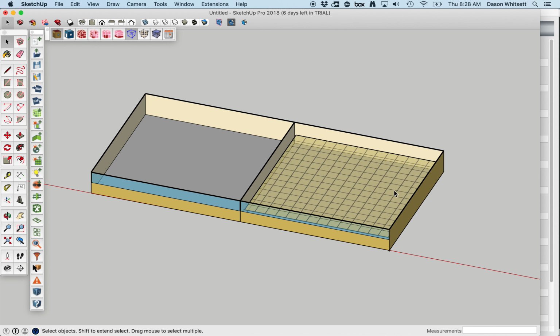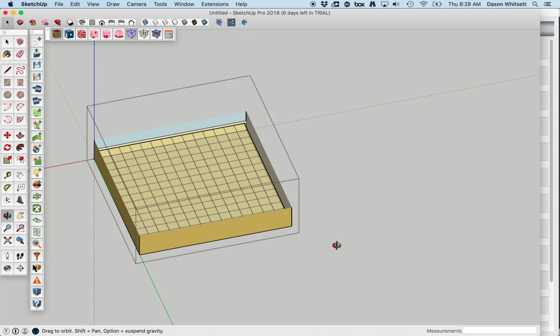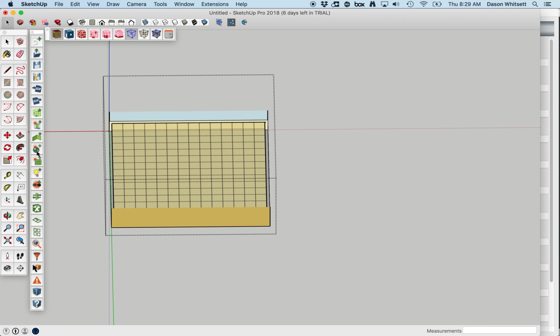The other tool that I need to trigger the daylight simulation in OpenStudio is a daylight control, which is this object here. I'm going to double click and edit my space one more time. Pivot around. I think I can get the one in there that I want to begin with. Select my daylight control. You can have up to two per zone. Generally, we'll put one in a larger room, one closer to the windows to control a zone of lighting that is more directly affected by the natural lighting, and one further away from the windows to control the rest of the lighting.